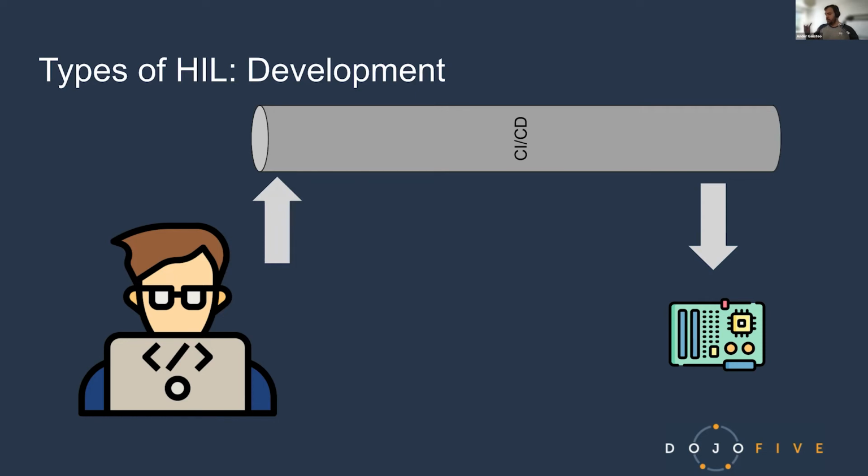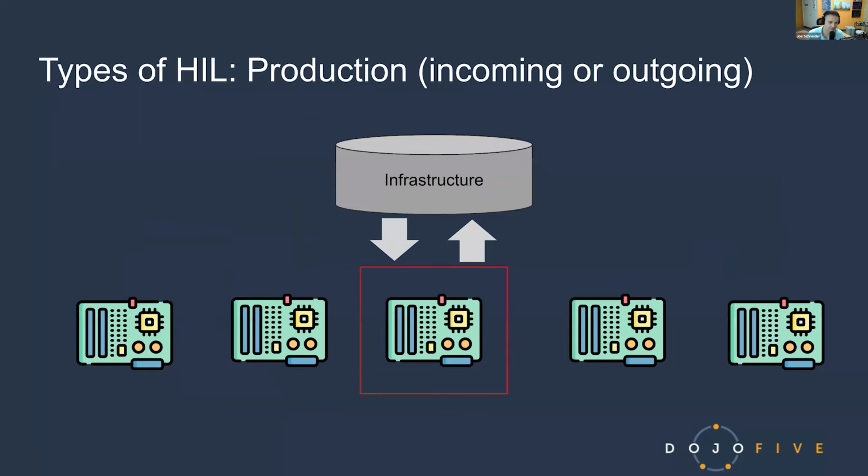And yeah, usually that's done connecting to the CI/CD and automatizing all the testing into your hardware in the loop setup. Usually, if the project is really big, you are going to have a bank of setups, and depending on the availability, then you can test your system one system at a time. Maybe you can divide the testing space into different systems in order to speed it up, and you can configure it according to your requirements. Yeah. Then the second one is on production.